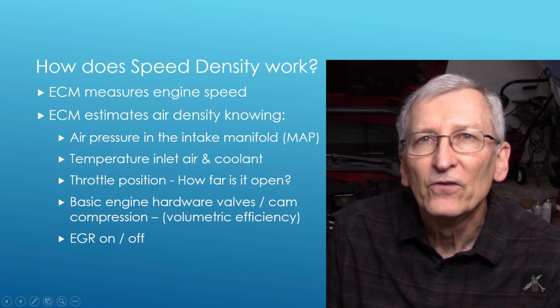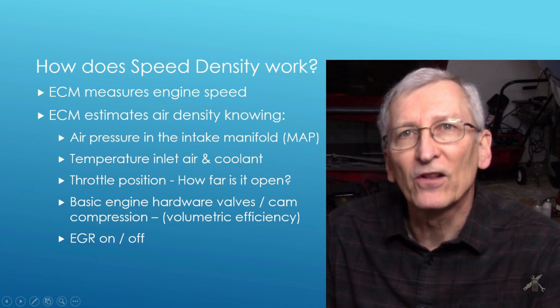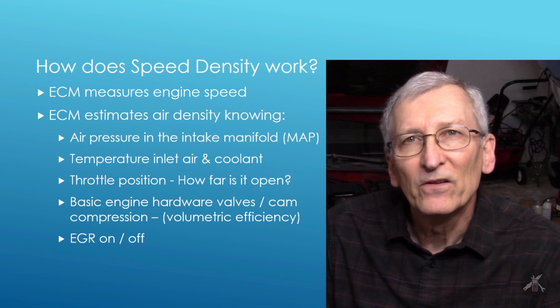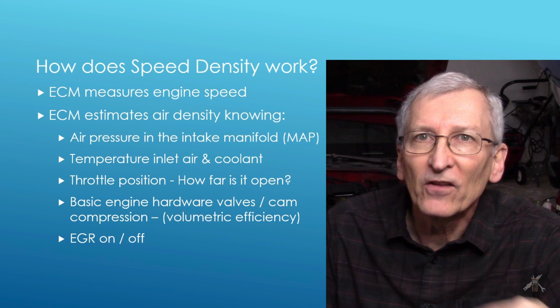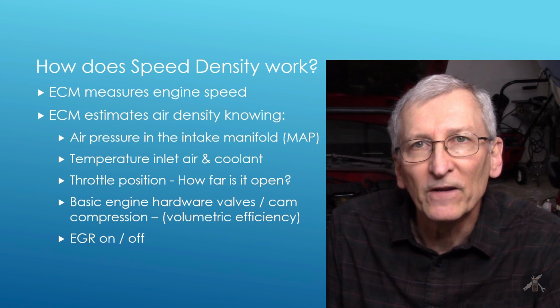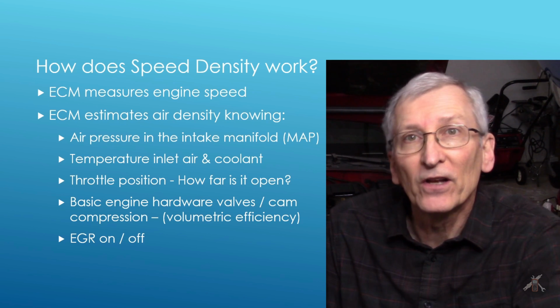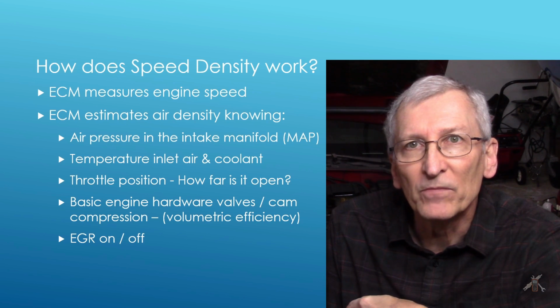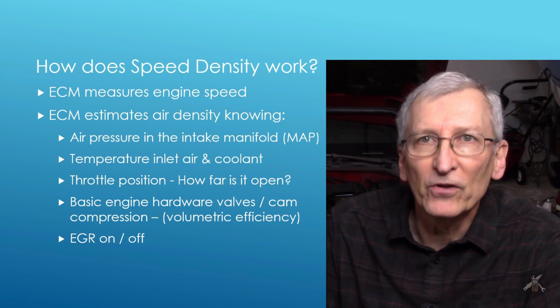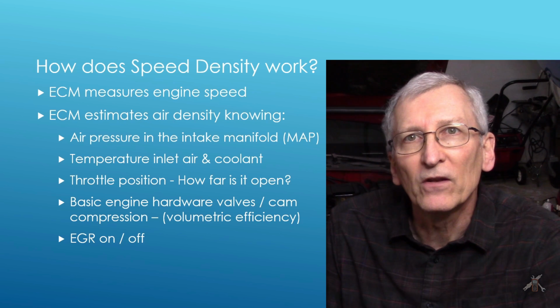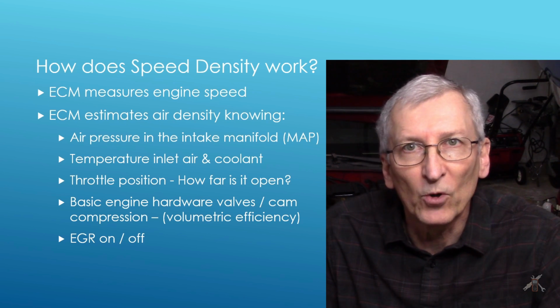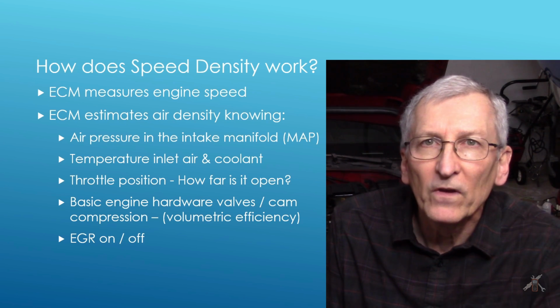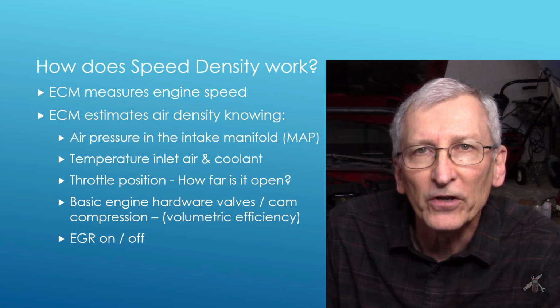In this case, your MAP sensor will still be there. It'll still be measuring how much air came into the engine from a density point of view, but it really can't tell what the volume is because it's only estimating. So if you make certain changes like cylinder heads or cams or whatever that changes the airflow characteristic of the engine, then you've got to start looking at, can I burn a chip? What do I have to do to tweak it to make the calibration work to correct the airflow calculation so it's more correct?